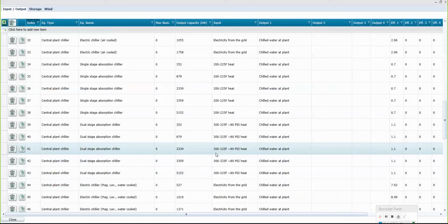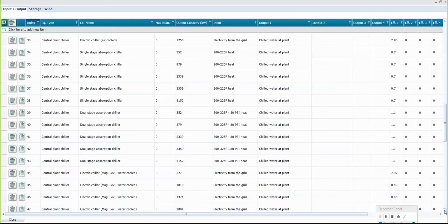It's somewhat helpful to know approximately what it does. Again, it's some kind of a chiller, and that's in the name. You should know maybe that this is often used in conjunction with something that produces waste heat. So if we have a natural gas turbine, or a reciprocating engine and we've got a lot of waste heat, we're going to want to use that during the winter to heat our buildings. We may want to use it during the summer as well, with one of these absorption chillers to provide cooling energy for our buildings.